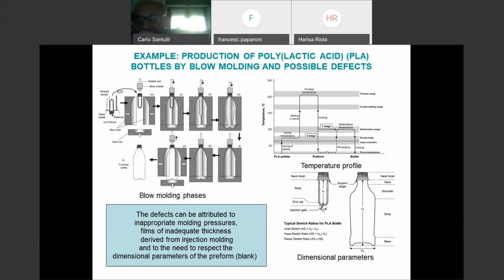Again, this is important, there is the limitation of polylactic acid, that we have a glass transition at 70 degrees. So we process them in the rubbery state, but we need to be careful at passing through the glass transition temperature and to cool down to the full temperature. And of course, the geometry has a relation between the velocity of the process and the times involved.